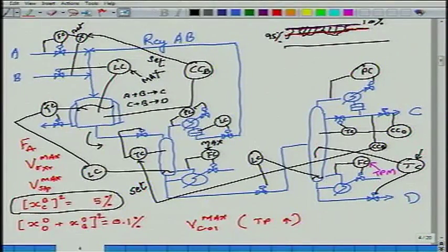Heavier components will cause temperature to rise. If the temperature is rising, what do you need to do to the feed? The stripper temperature controller will say increase the reactor effluent flow rate. Reactor effluent flow rate increases, level starts to go down in the reactor, that starts sucking in more B. Level controller of the reactor starts sucking in more B. Ratio controller ensures that more A gets sucked in.